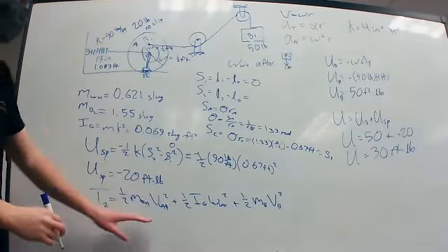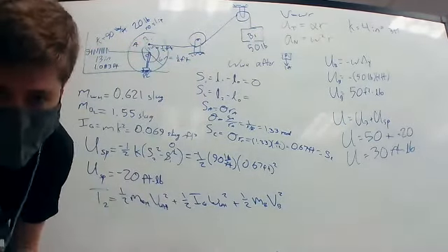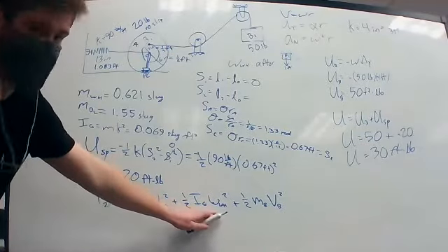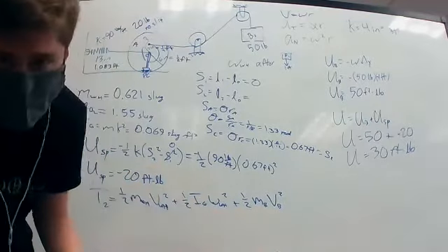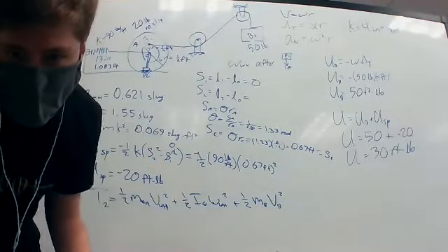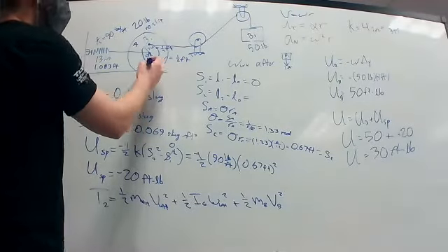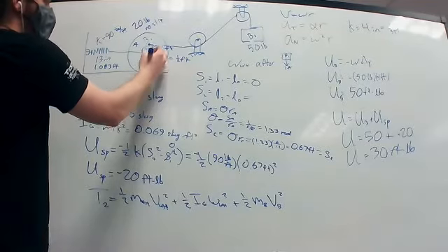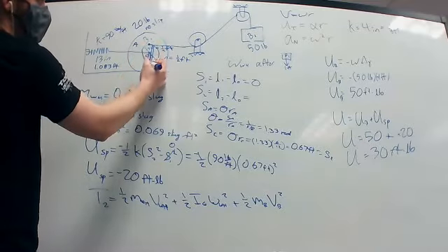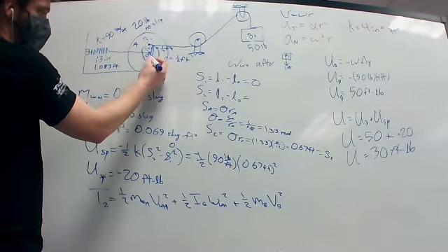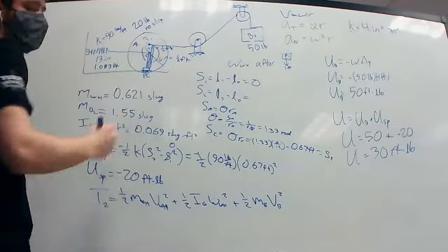So yeah, velocity is equal to omega times R, sorry. And so then this one is already in terms of omega. And then velocity of the block is going to be equal to omega of the wheel, but times a larger radius as the radius extends all the way up to this point. So we have a smaller radius from point of contact to the center and a larger one from point of contact to where the tension cable meets the wheel.